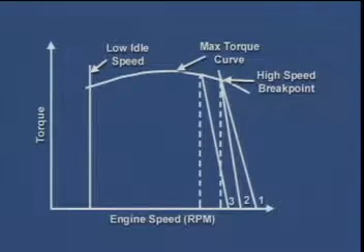The alternate droop feature allows the droop characteristics to be changed for high engine governed speeds and for the all-speed governor. Less governor droop provides a more responsive governor for more precise engine control. More governor droop provides smoother shifting and smoother mechanical clutch engagement.